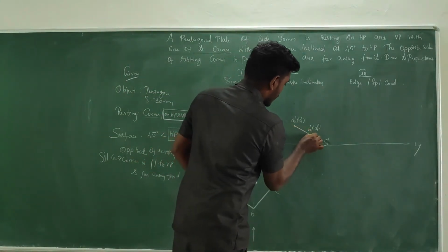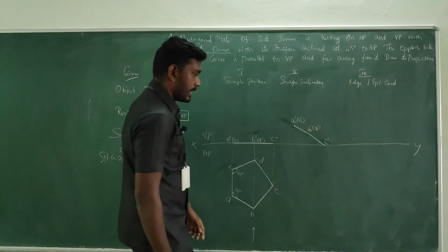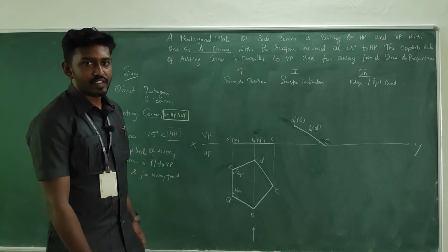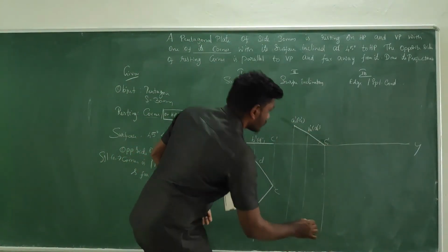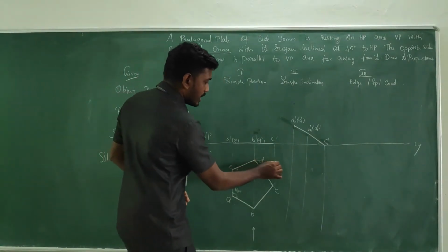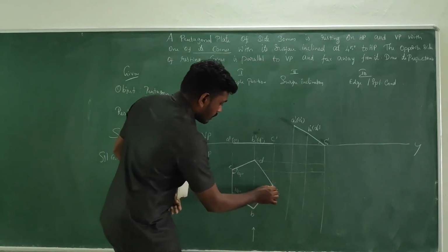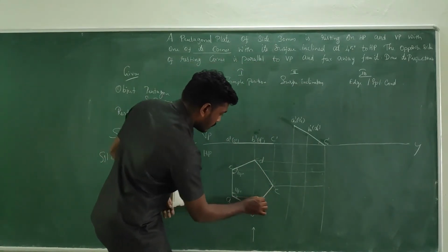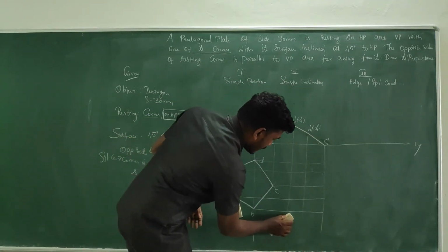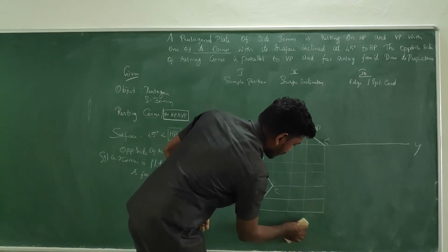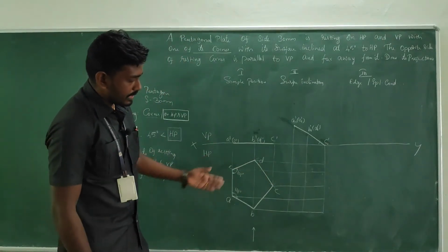Between A to C, go for a straight line with a dark one. With your HP pencil, you will get the trace in the front view for the surface inclination. Get the projector in order to get the top view. From the previous stage, get the projector. It should be a very good horizontal line. Take the projectors. You will form the things like this. Remove all the extra lines coming above the boundaries.